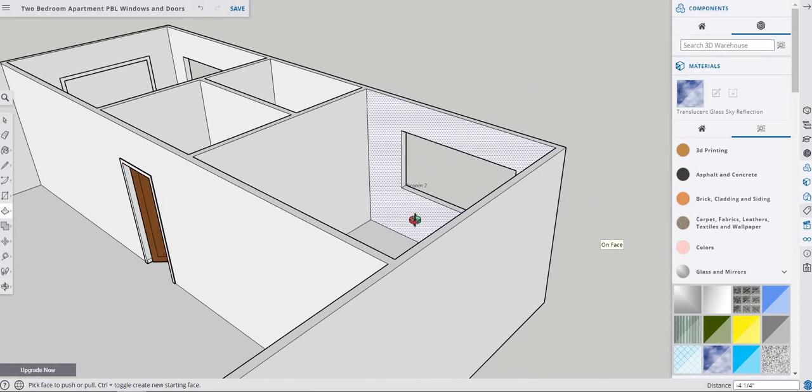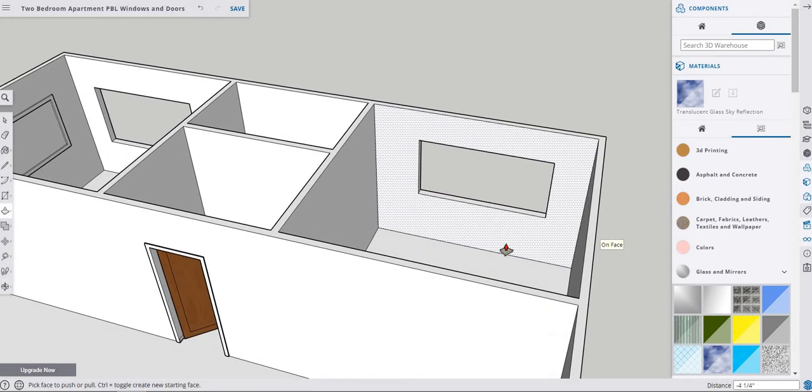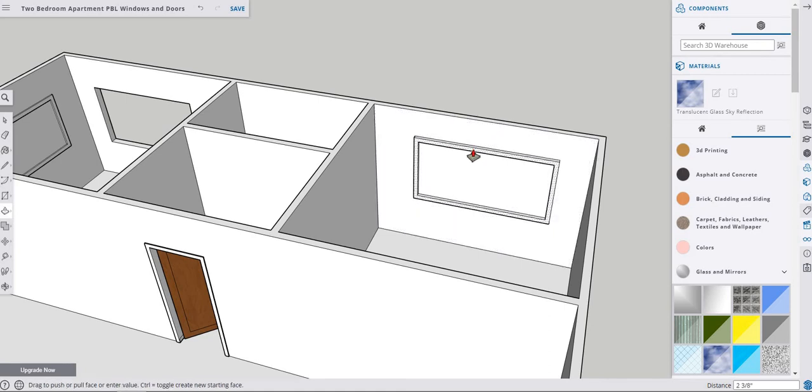We're going to go rectangle, edge to edge. Okay. Corner to corner. It seals up the window, or appears to. F again, edge here out. We're going to go 3 inches. Push pull out 1 inch. Okay, remember 1 inch. Enter.